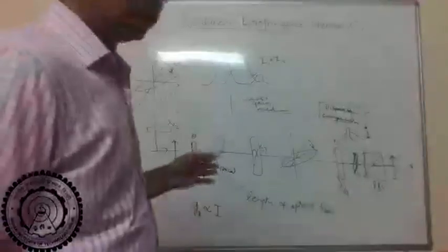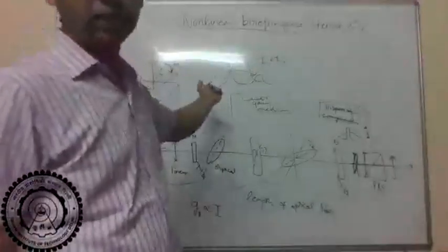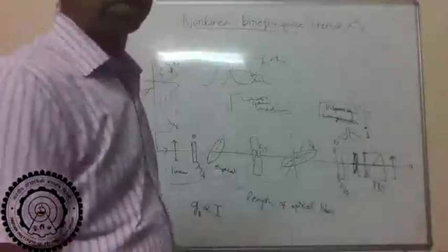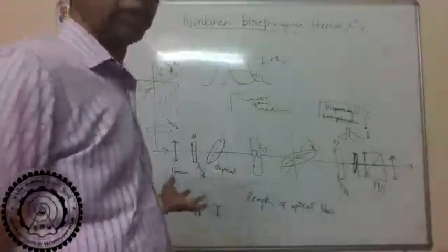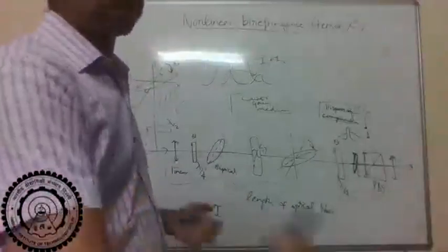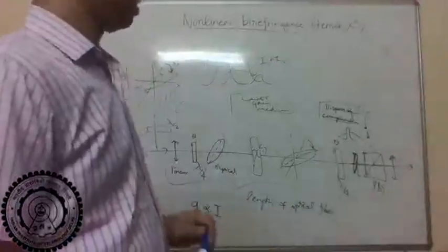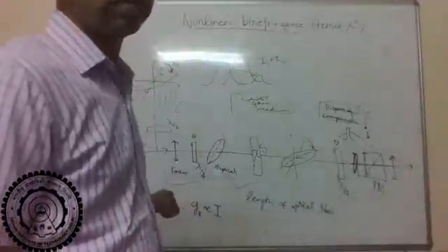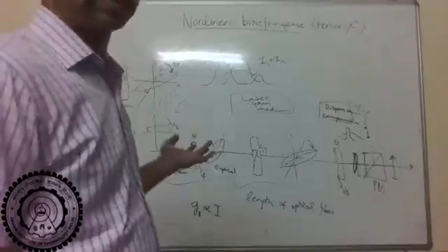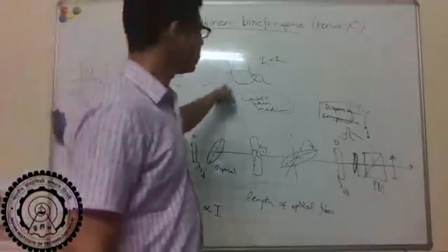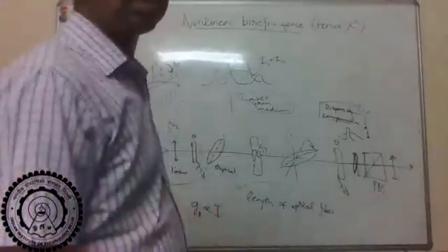So the point is, you actually want a broadband response, right? If you are looking at ultrashort pulses, they have a very broad spectrum. And whatever nonlinear interaction you're using had better have at least the bandwidth of the pulse. So Brillouin is very narrow. Typically the Brillouin gain line width is a megahertz or something, but if you take femtosecond or picosecond pulses, the bandwidth is terahertz.